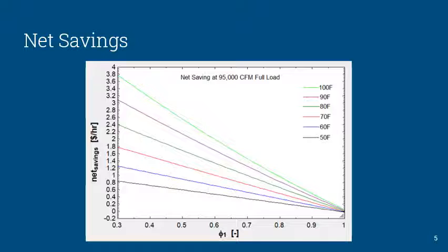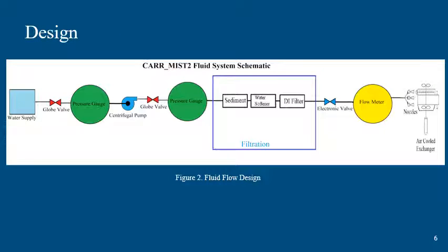The EASE code calculates how much water must be introduced to take the dry bulb temperature down to its wet bulb temperature. The energy savings of an evaporative water mist system can be very significant if sufficient water can be evaporated. The system is used to chill coils on the 30XV chiller.